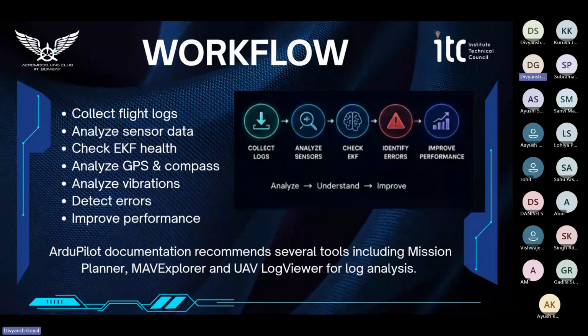The workflow of flight log analysis is that firstly, you will have your flight and get some flight log data. You will analyze your sensors and check whether there is any error in a sensor, check your EKF or identify the error, and finally you will fix those errors and improve the performance of further flights. For this, we have some software like Mission Planner and UAV Log Viewer for viewing your flight logs to do the further analysis.